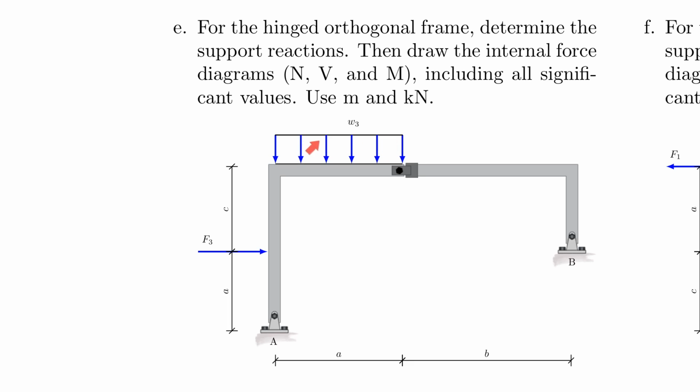In this case, the system only has load on it on the left side. This is to make your life easier so that you can quickly identify your two equations with two unknowns to find your first support reaction and then move on. And then everything you learned from before in the homework applies as well. Once you found the support reactions, it is really not different. So of course you need a reference fiber again, because that really determines how your diagrams are drawn in terms of positive and negative regions. So that completes this problem.